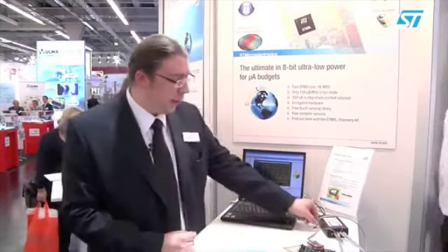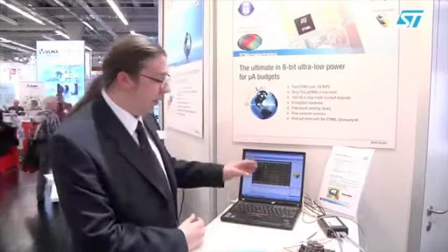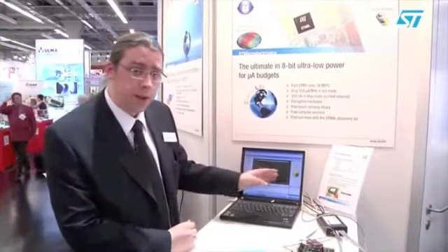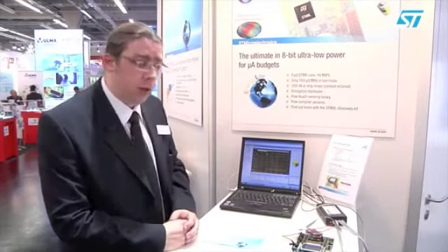It is possible to link this directly to the debugger as well, so you can supply some triggers back from the application into the debug interface and link the information that you get for power consumption directly back to the routine that you're executing in the application. This allows you to ascertain immediately if you have correctly entered the low power mode as you've designed your application to do, or if you have some software bugs that mean you still need to work on that a little bit and get the power modes sorted out correctly.